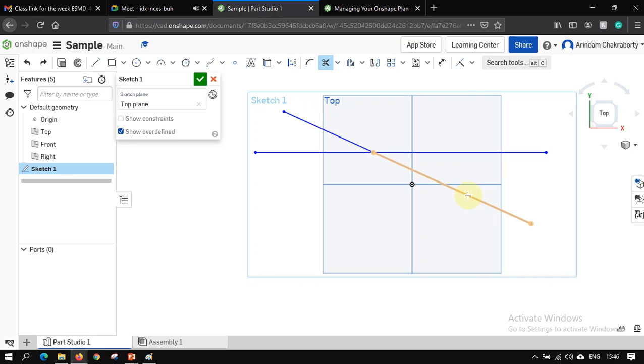What he told is that by trimming, the entire line from the intersection point gets deleted, but he asked me, if I need to eliminate up to this one and keep this one, what to do? The same, there are two ways out. What you can do is bring this line to this one: just select the point, select this head and bring it to this line. Now, how can you understand that you are hitting on this line or intersecting? Just see that a dash line is appearing. Can you see a minus sign? Yes, sir. So that means the point is on the horizontal axis. Clear?